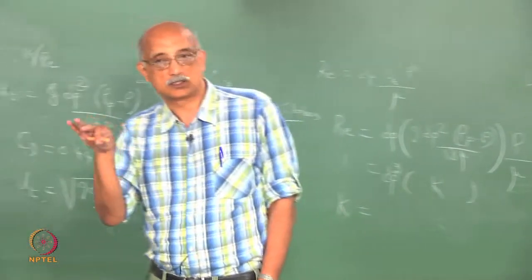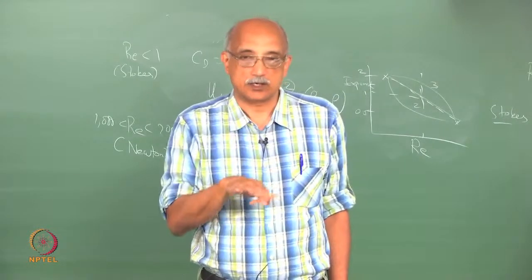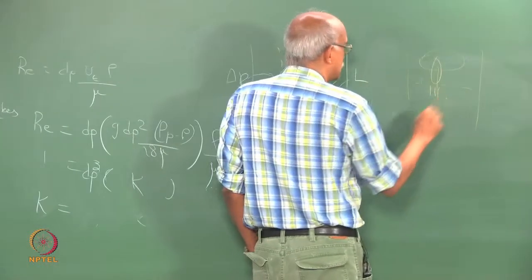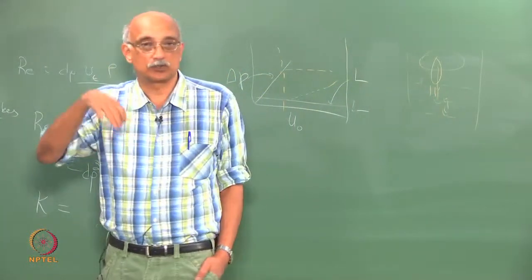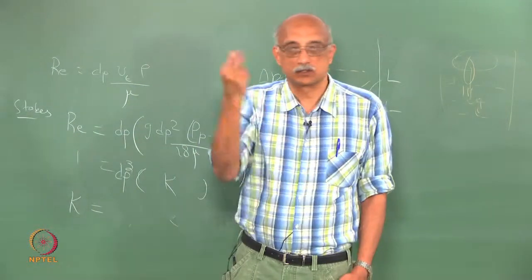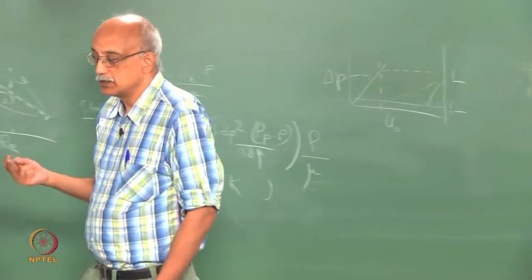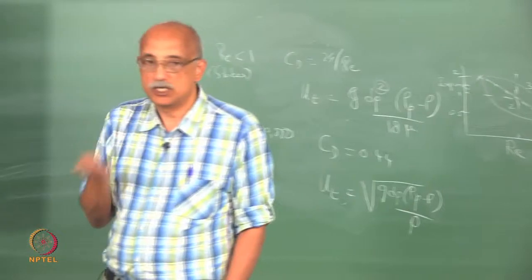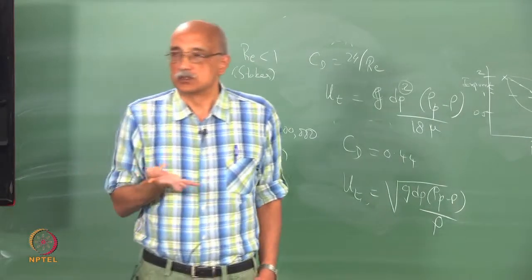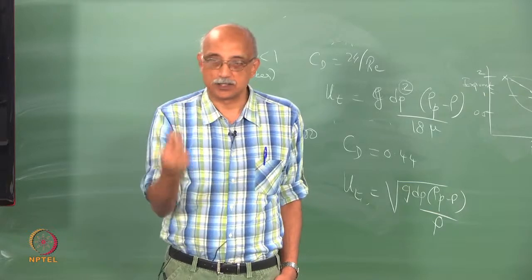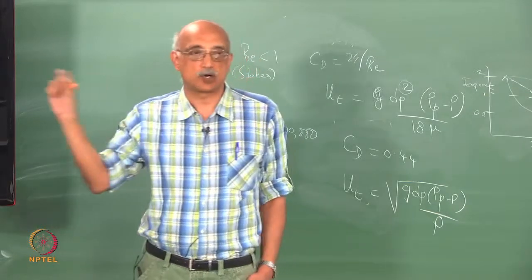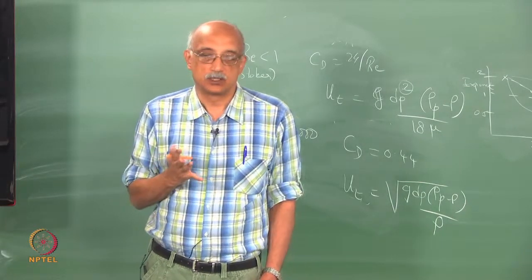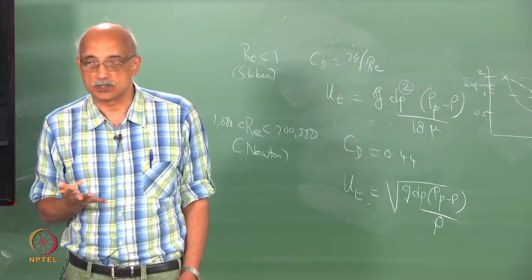then clearly its direction of alignment is going to make a big difference to its settling characteristics, because drag is based on the surface area that is perpendicular to the flow, right? So in a configuration which minimizes the projected area that is perpendicular to the flow direction, you are going to get minimum resistance to motion. So a droplet that is like this will fall quickly, whereas the same droplet, if it is horizontally aligned, will move slowly, and that is just based pretty much on projected particle area characteristics.